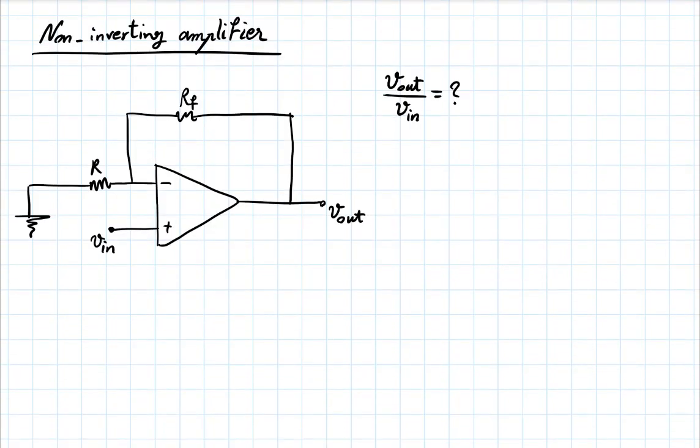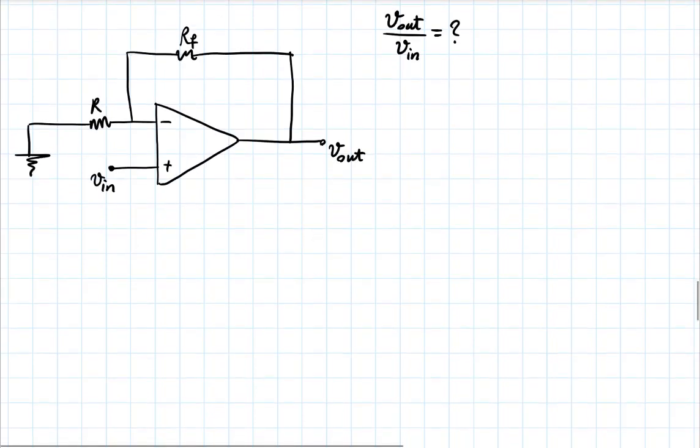I think it's good that we reviewed that. Now let's look at what's happening here. So I have the starting point down here where I know that the input voltage Vin has been applied. And if the circuit has been made such that the op-amp stays within its linear region of operation, then there is no difference between the two input voltages.